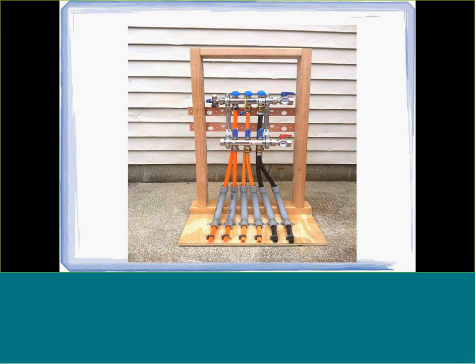There's just a picture of a mock-up of a manifold system. You can see the sleeves coming where they would come out of the floor, and then the short attachment distance between the sleeves and the bottom of the manifold. And that is mounted 16 inches from what would be the finished floor. So you can see there's a short distance there. So make sure you get it far enough up off the floor so that you can get the tubing connected.